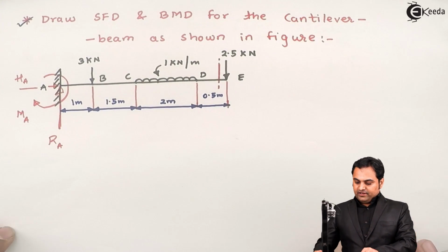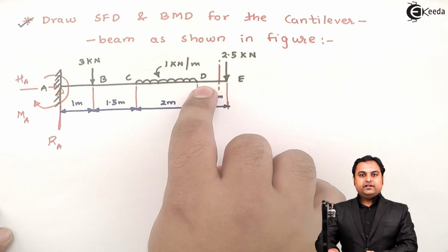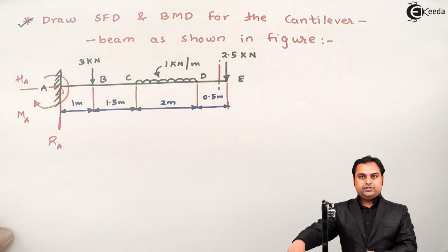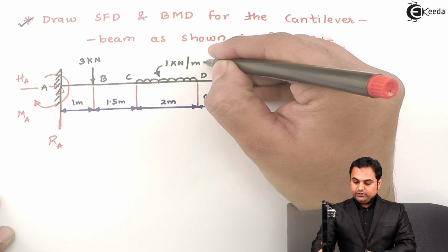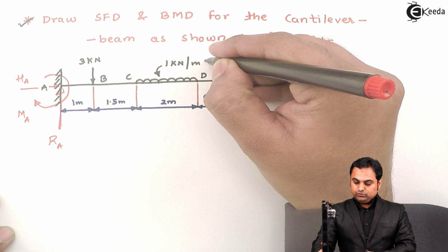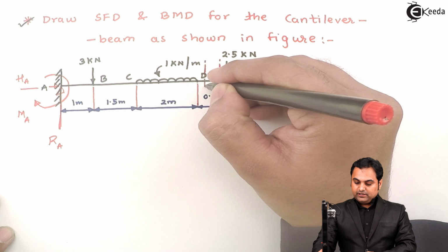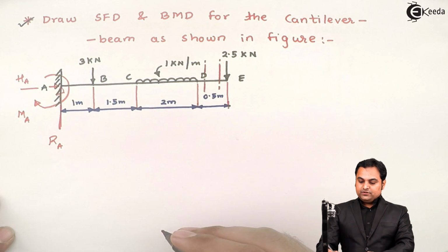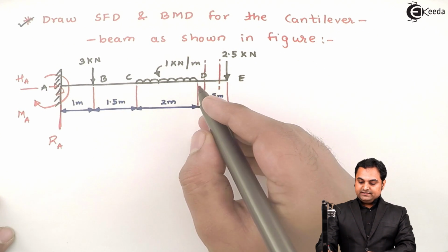So now here I have calculated shear force at point capital E. Next, if we see between point E to D there are no load, so the value of shear force will remain constant up to point D, that is, if I take the section to the right of D, then up till here the shear force value will remain constant. So SF at point E and SF at point D both are same.